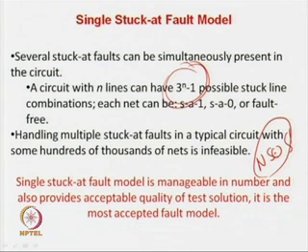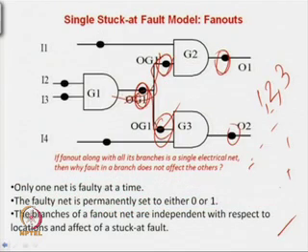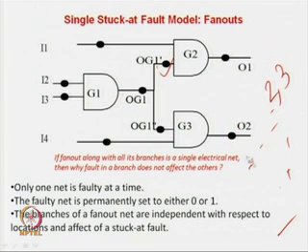So again, statistically it has been found that if you consider a single stuck fault, what is a single stuck fault? You have to think that only one fault exists at a time. I will consider all the stuck faults, that is true, but first I will find out that this fault is not there. Then, if I find that this fault is not there, very good, I will test for the next one. This fault is not there, then it is fine, and so forth.